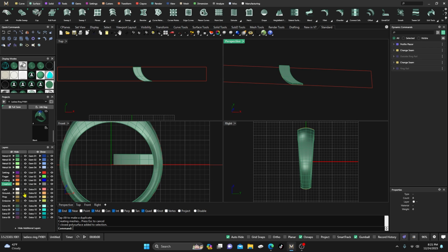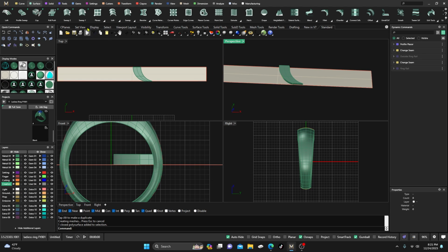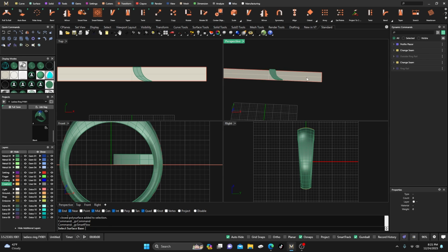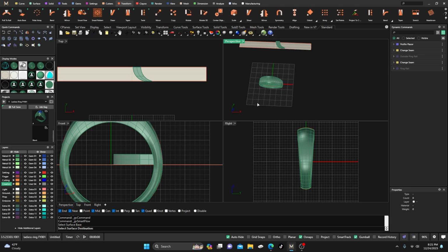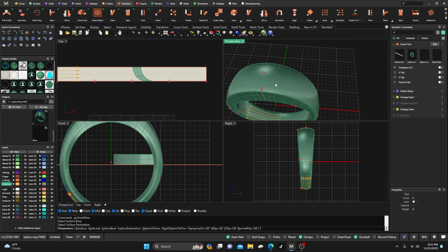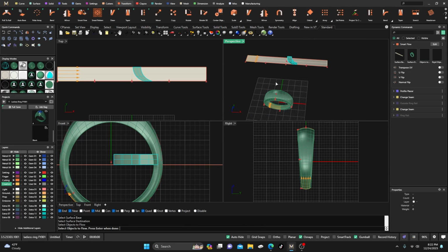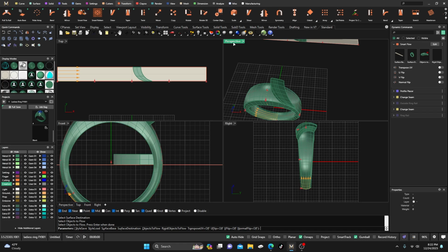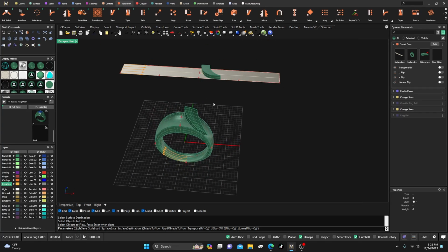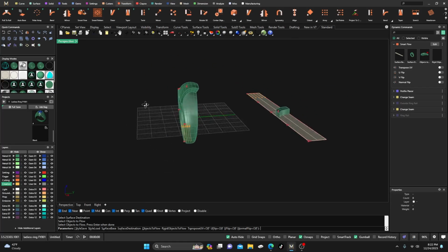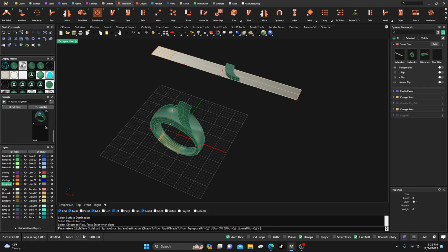Bring back that auto base that we did, and then go to transform, go to smart flow, select on that, select the base surface, which is the one, the auto base, and then the surface we want to flow it on, which would be this one. Go to objects, select on it, and then hit enter, and now it places it at the top, right? So there's all kind of ways to be able to change it up or whatever. So hopefully that answers the majority of your questions, I think. I hope.